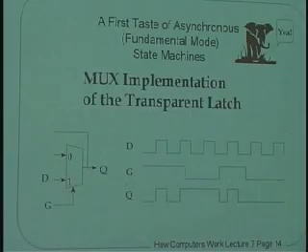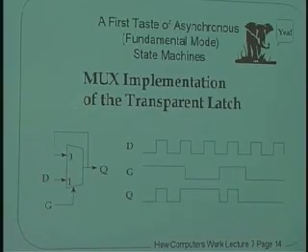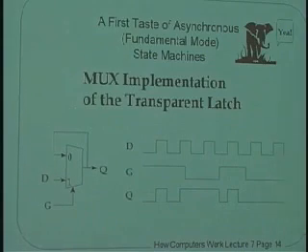Okay. So let's start to build some memory out of this thing. We have in our hands a hazard-free selector. Kind of a cool thing. G can go up and down. We've called it SG now. And into the one input, I'm going to feed a data input called D. And out of the output of the selector, I'm going to take an output and I'm going to call it Q. And here's how it works. We're building the memory here. When G is high, when the gate is high, the output Q is going to do what?